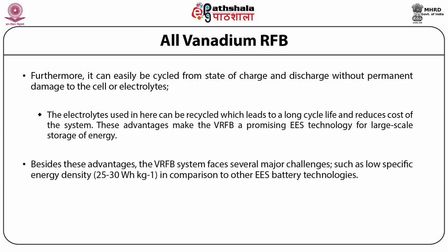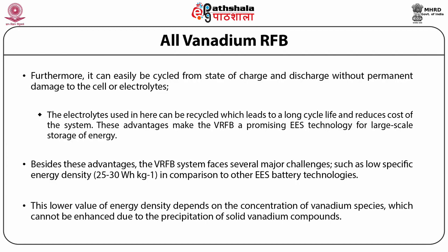Besides these advantages, the VRFB system faces several major challenges, such as low specific energy density in comparison to other EES battery technologies. This lower value of energy density depends on the concentration of vanadium species, which cannot be enhanced due to the precipitation of solid vanadium compounds.